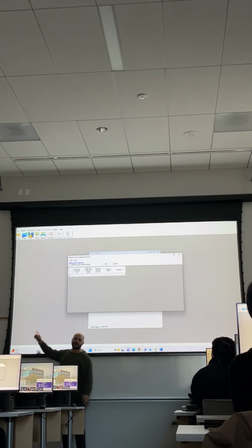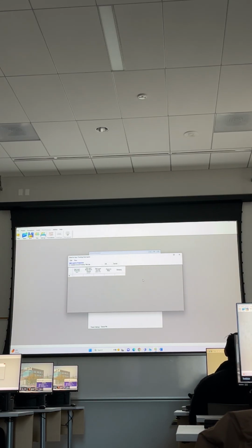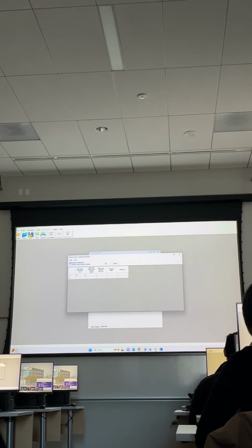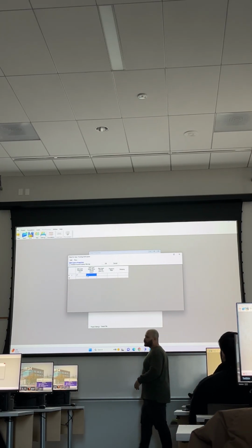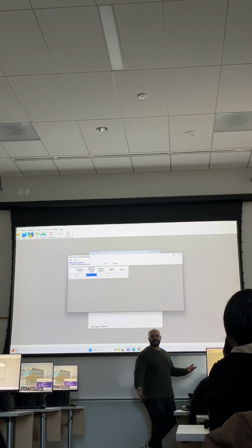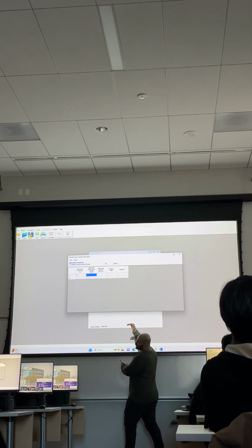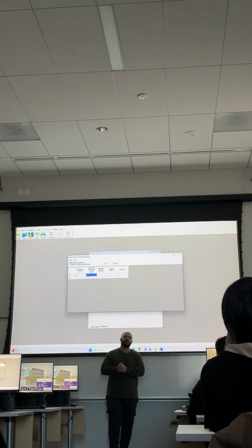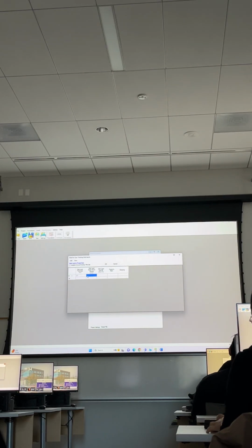But usually Professor Sham preferred to assume it just 1.7, which is around 1 foot lower than the full length, because he assumes that we can compact the soil in the upper part. So if your foundation is 2 meters thick, you can use up to 1.7 because we don't trust the compaction process in the upper part.